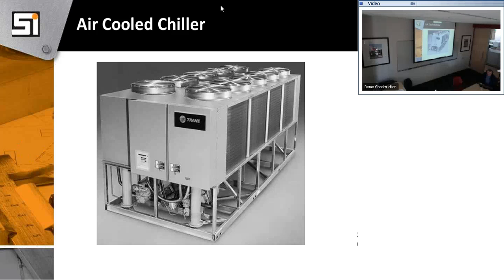Once you go into water-cooled chillers, he said water treatment. That becomes a big deal. Scale it. Yeah, because you've got water flowing through this iron pipe, and it's constantly corroding, and it's exposed to the elements. There's a difference between closed systems and open systems. A closed system is something that's not exposed to air. Open is like open water, cooling tower. That water is exposed to air, so it's taking all the junk, whatever. Plus you have evaporation, so you're using water.